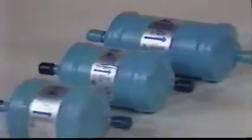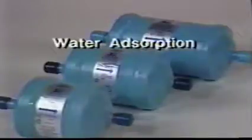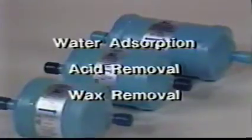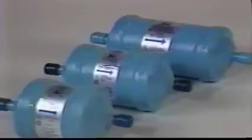Liquid line dryers are available in a variety of designs, each with its own capability. Some have higher water adsorbing strength, while others are specifically designed for acid removal. Others are designed for greater wax removal properties. These are particularly useful in R22 and R502 systems. And of course, since flow rate is important to all filter dryers, a variety of sizes is available to match the system flow requirements.